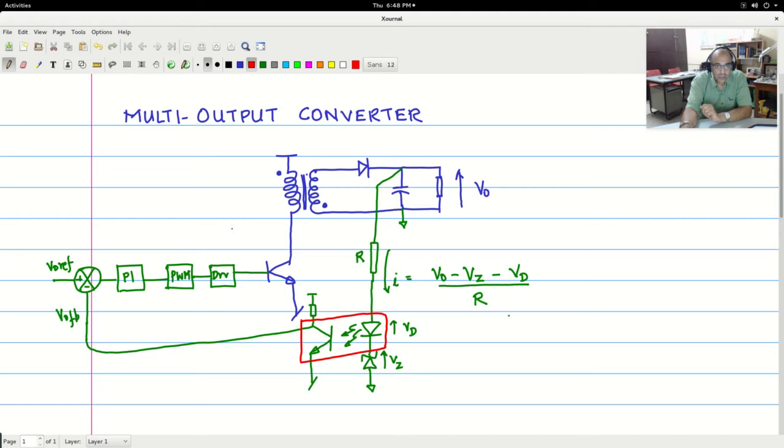Now, the next important point that you should see is that with one control topology circuit, you can control one set of switches, either this or, in the case of the push-pull, full bridge and half bridge circuits, you can control the other set of switches too, because the duty cycles are coupled in the sense that the same duty cycle can be applied to the other set too. Only thing is that they are mutually exclusive.